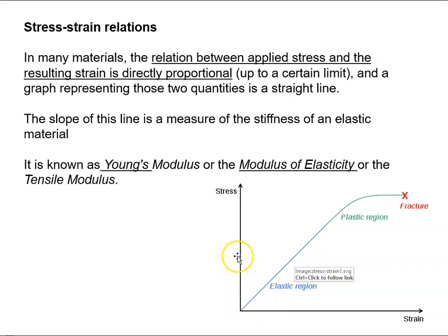Imagine if it was 4 units of stress and 2 units of strain. That would be a sharper, a greater angle. 4 and 2, 8 and 4. And that would produce a linear relationship that ran like this. What that would be showing us is that if it was doing 4 and 2 rather than 4 and 4, this steeper line is a stiffer material because it's taking more stress with little strain.